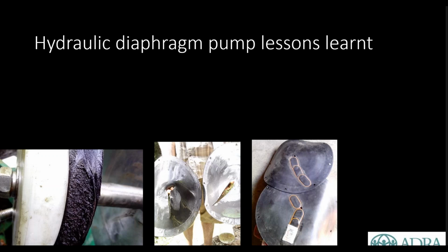And then the middle photo is actually a diaphragm that's split, and it appears that this is because the bolts may be done up in a regular pattern, maybe in a clockwise motion, rather than doing up one bolt, say here, and then the second bolt on this side, and then another bolt down here, and then a fourth bolt up here, that it's actually possibly been done up in some sort of a circular motion.